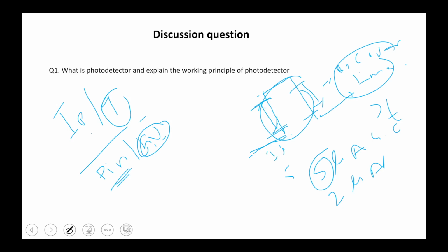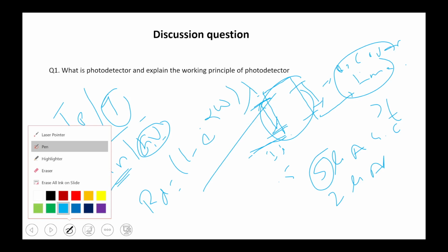Power absorption by power input is equal to 1 minus e to the power minus alpha w, where w is the depletion width. I think this is the relation. Is the responsivity equal to 1 minus e to the power minus alpha w into lambda?